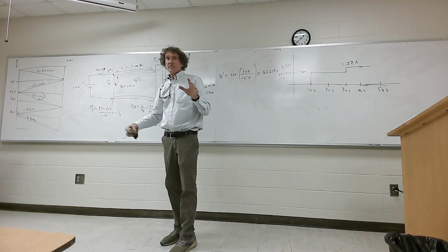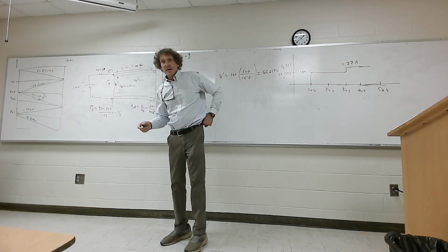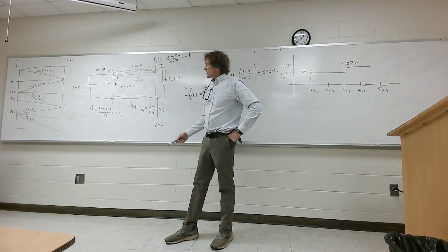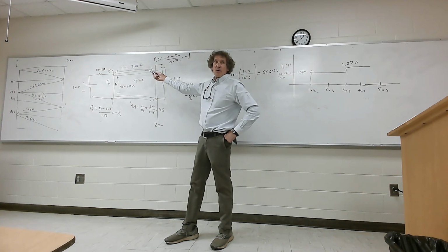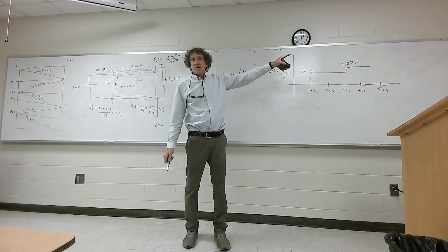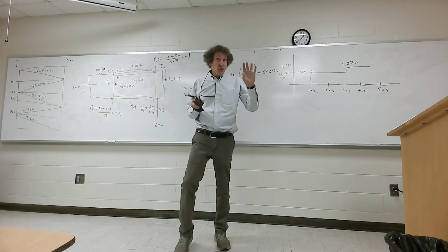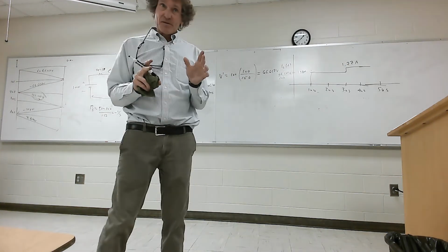Now I'll ask you an obvious question. We could keep going, right? But where's this going? In the long run, what is this going to settle in at? It's just going to be 100 divided by 50, or 2. Can you see it's going to be getting there? And it'll keep on doing that. But that's the bounce diagram. It's the current in the load. It's not the voltage at the load.